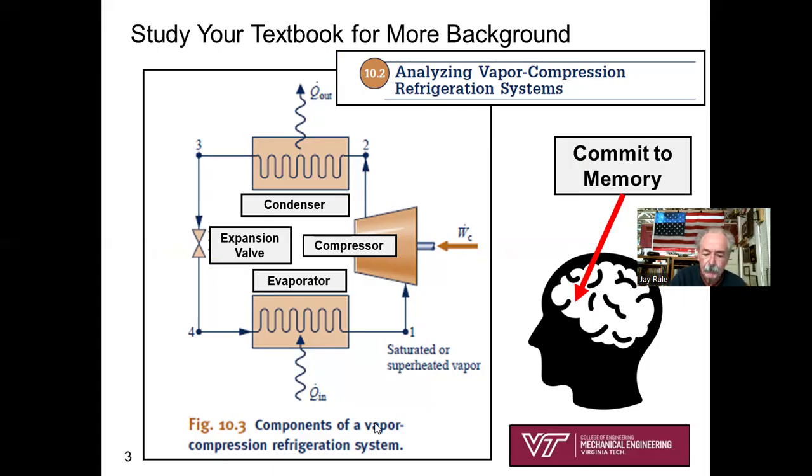Why do we call it vapor compression refrigeration cycle? Well, refrigeration, we're transferring heat from cold to hot. Got it. Why do we call it vapor compression? Because this refrigerant that we're using is a phase change substance, and in part of the cycle, it is a vapor. In other parts of the cycle, it's a liquid. So the refrigerant is changing phase as it's going through this cycle.